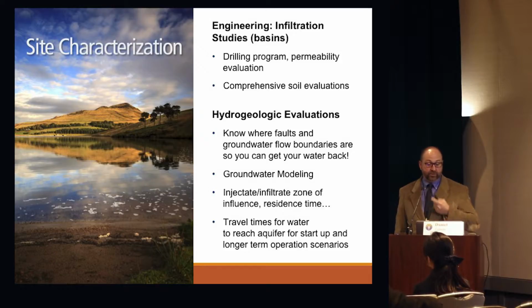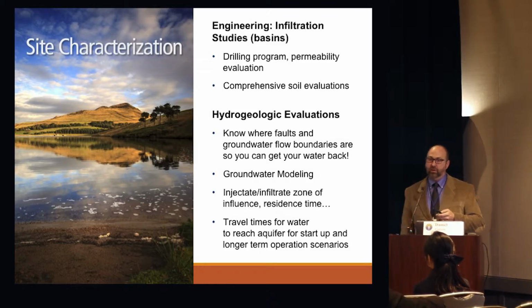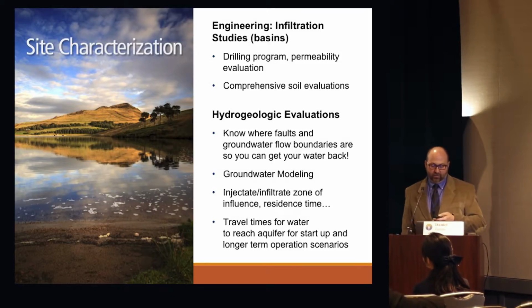Obviously, you want to get out there and start doing your field studies. A big one is know where your faults are, and know where the groundwater is going to flow to. I could do a whole slide on a couple of case scenarios where there's success and there's abject failure because they didn't map faults and groundwater went where it wasn't supposed to go, and the recovery wells were sucking air, so to say. You don't want that to happen.